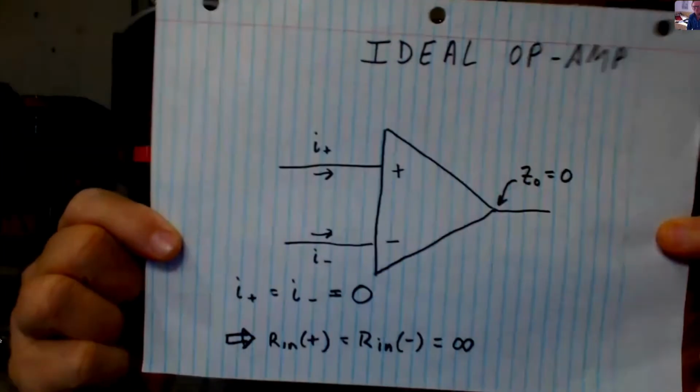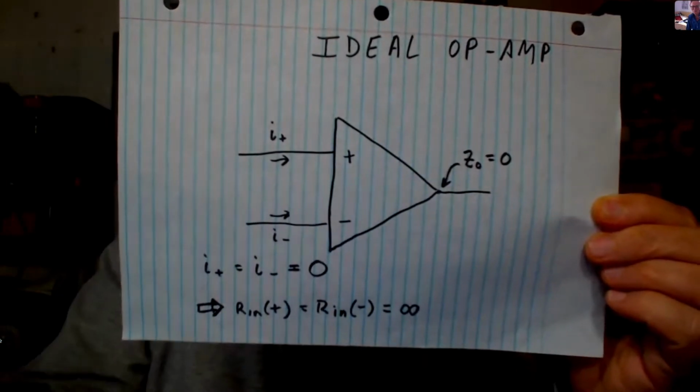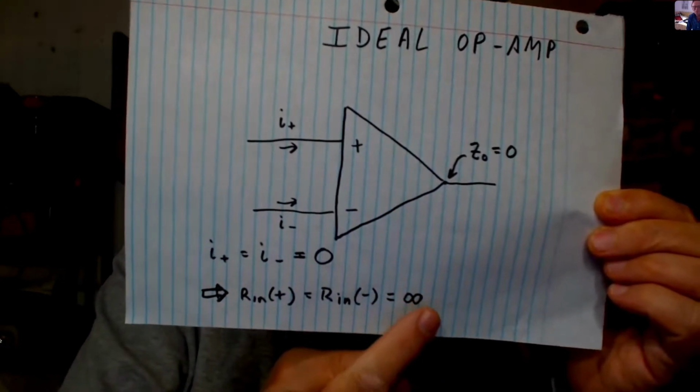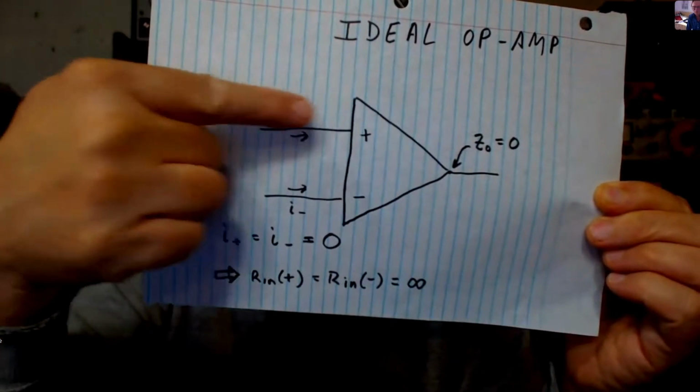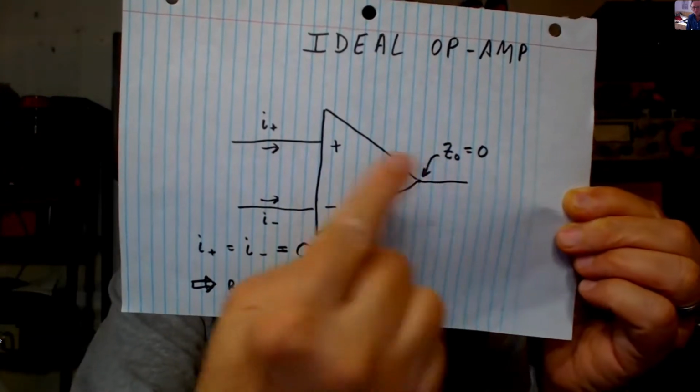Well, I should, while I'm thinking about it, also point out one other set of assumptions that we usually make about operational amplifiers, and then we can relate this back to what your question was about normal amplifiers. Ideally, an op-amp would have certain characteristics. Ideally, that A, which I said was very large, would be infinity. Ideally, there's no current flowing into these terminals, only coming out of the output.